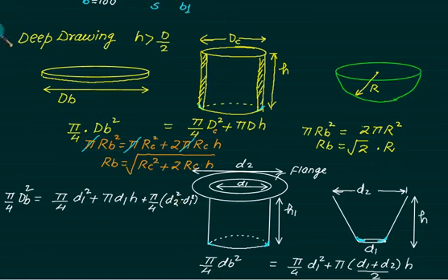Now, when you are doing the deep drawing operation, this job is placed on the die. The tool is pressed. The punch will move downward. But there is no shearing action. This die will be pressed. But you are not getting the final cup in a single stroke.